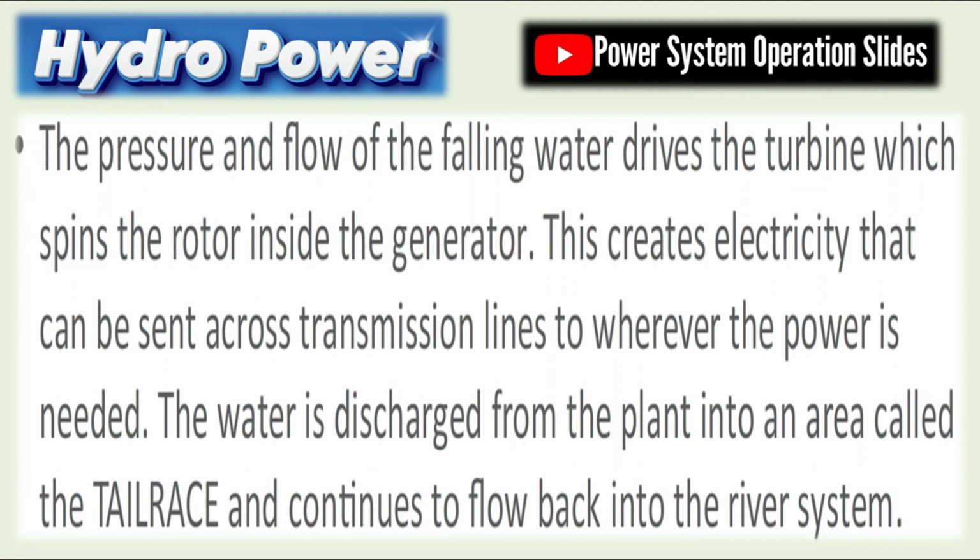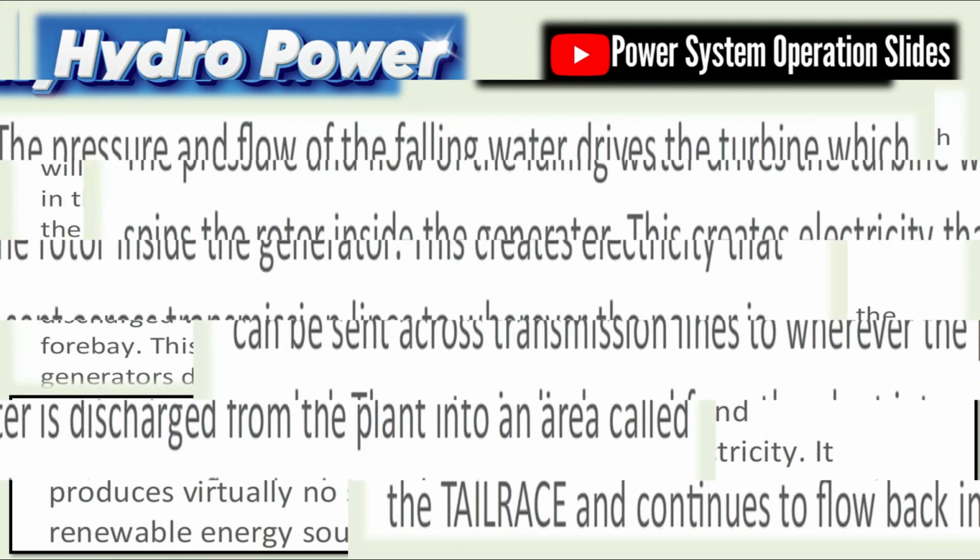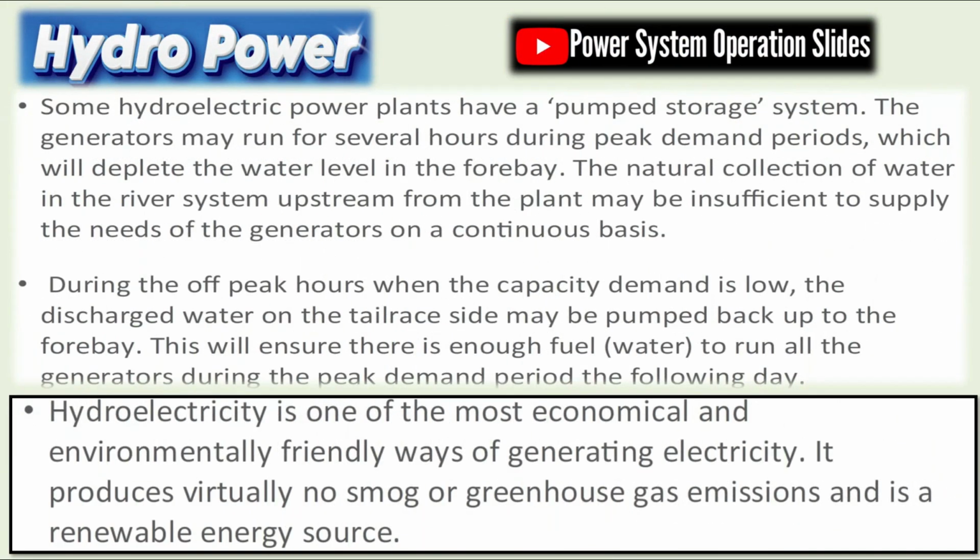Hydraulic turbines include Pelton, Francis, and Kaplan types, each suited to different head and flow conditions. These turbines convert the potential and kinetic energy of water into mechanical energy, which is ideal for both base load and peak load applications depending on reservoir capacity.